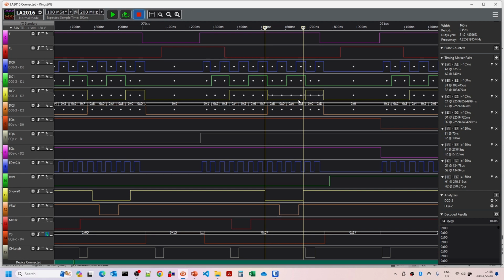There was a problem I had, and it was because the configuration of the PLD takes hexadecimal values, and I was putting 10, 11, 12, and obviously that was counting it as hexadecimal, and so it was resulting in slightly weird results. So the clock circuit now seems to be configured properly. I'll just show you a few of the issues I had to solve.